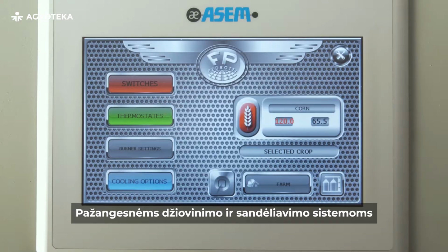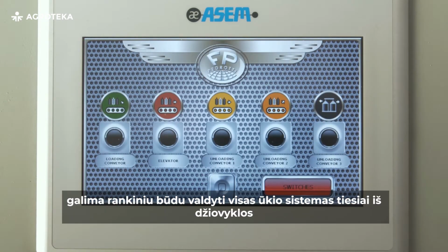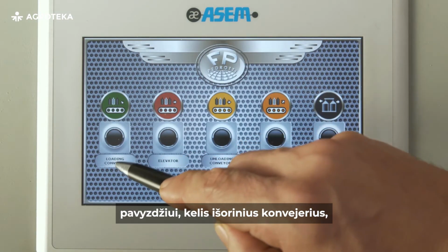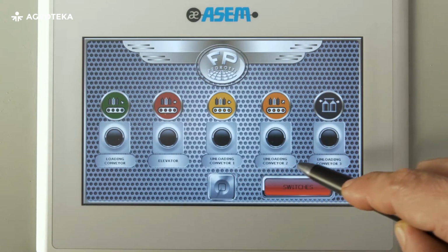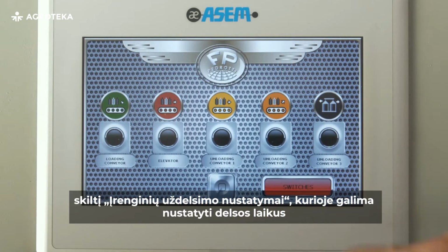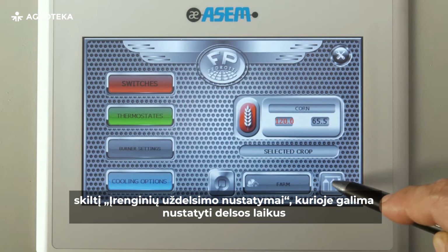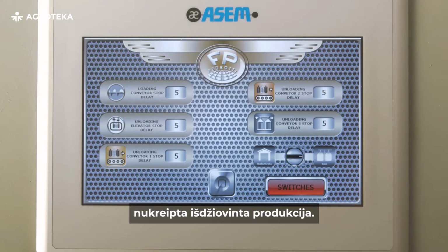In the more advanced drying and stocking plans, we provide a farm page where it is possible to rule manually all your facilities from the dryer, such as multiple external conveyors, elevators, silo fan, and so on. Besides the farm button, you will find a tab to enter in the facility's delay settings, where you can set your delay preferences for the manual mode and the building destination where the batch of dried product will be stored.